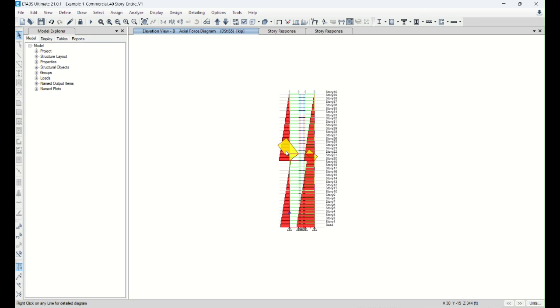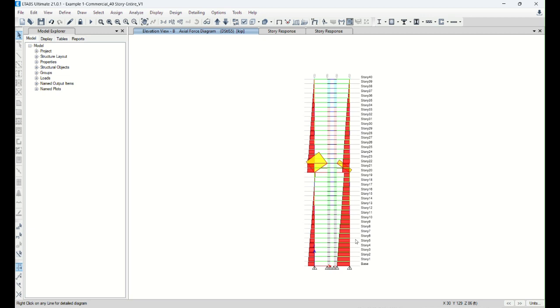Now include the wind effect, and with the combined effect we really have to design one more time, making sure every column is working. But most likely those columns tied through the outriggers are not going to work, so then typically we need to size up, increasing the size based upon our wind effect.